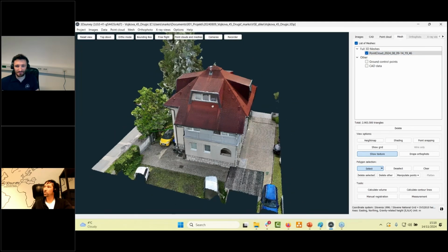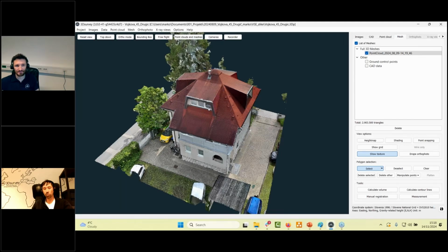So getting the mesh of the material depends on what kind of source you have as an input. If you have a SLAM or laser scanner, it's pretty much the same as with photogrammetry, but it depends on the input. If you have a good point cloud, you will also get a nice mesh from the interior. What's great is if you have the option to import the point cloud with normals. This really helps us to create a nice interior mesh from inside.